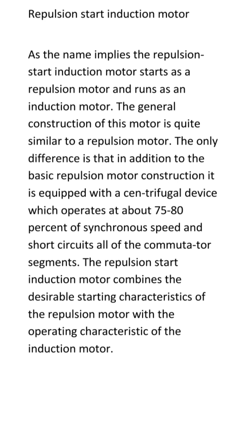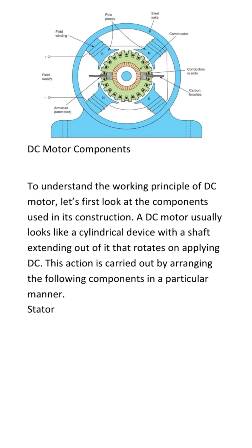Such motors are suitable for commercial refrigerators, compressors, pumps, hoists, and constant speed drives, particularly those which have high inertia and a heavy starting period. The usual rating is from 1/3 kilowatt to 12 kilowatts, but for special applications, ratings as high as 30 kilowatts are available. Although this kind of repulsion motor's price is high, this device is safe where the brushes are run quietly.